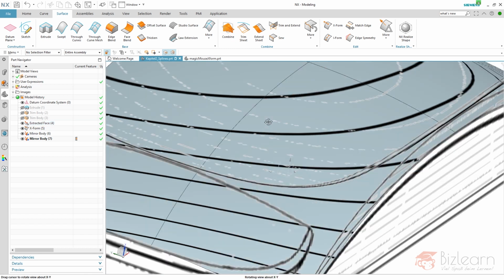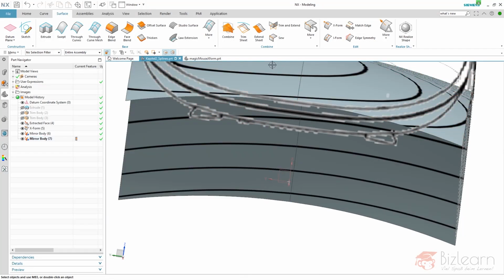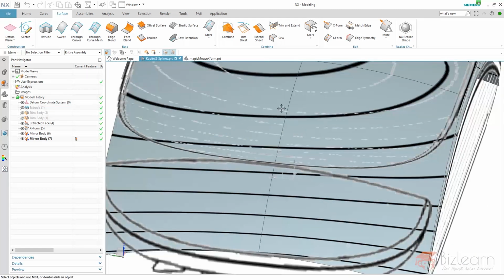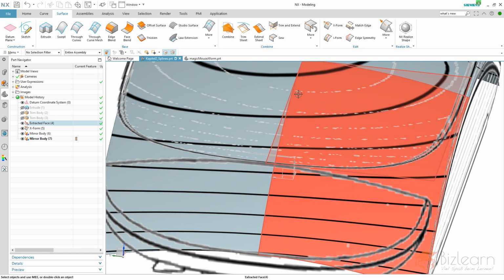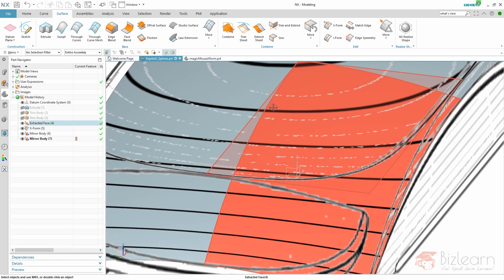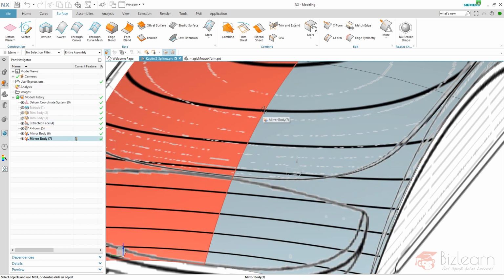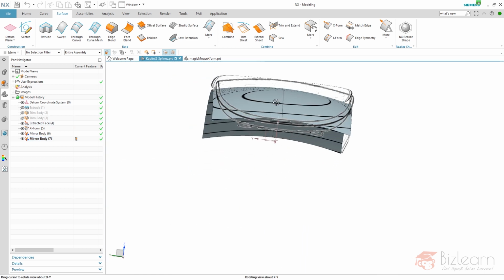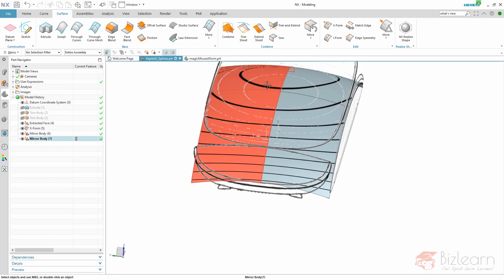Well, tangency means that if you create a section here on your surfaces, the resulting lines would be tangent, as all of you are familiar with. But curvature consistency means that it's not just a tangency, it means that the radius value on each endpoint of our section are equal. And that's the case because we've created a mirror.